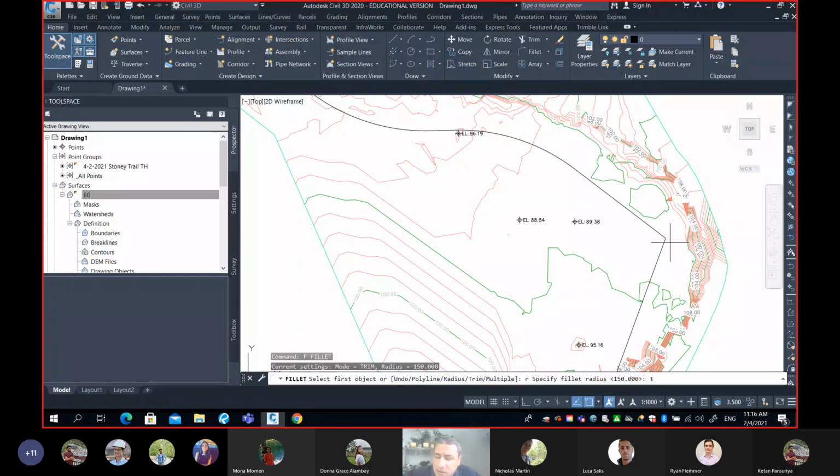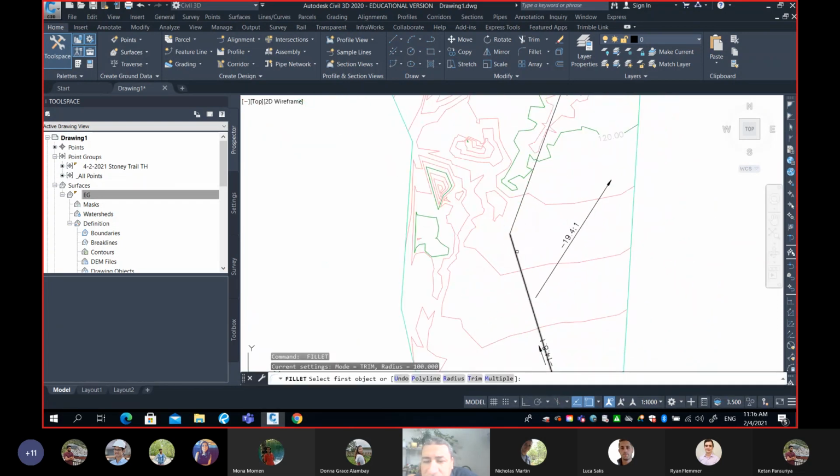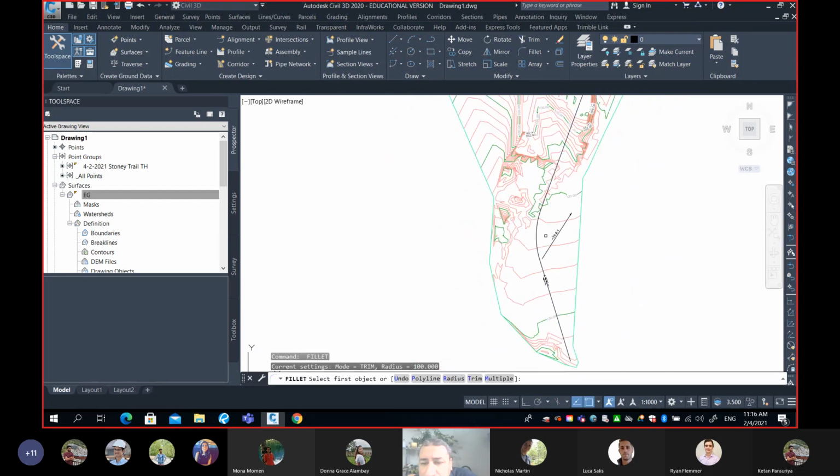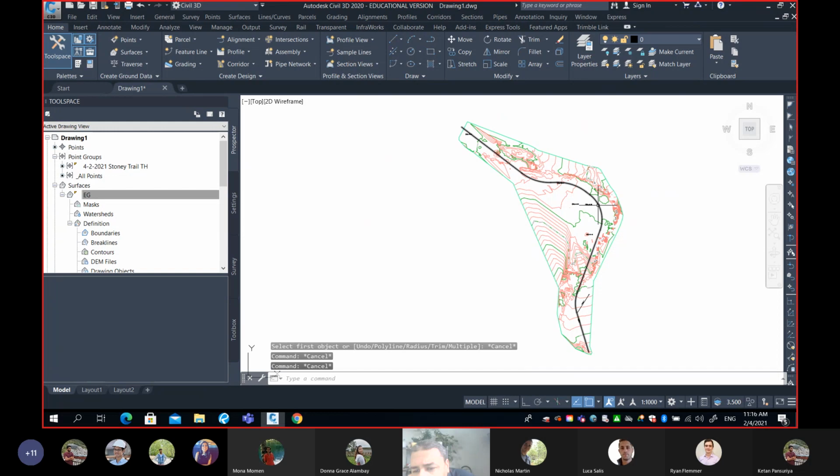So that's very big. So let's say fillet radius 100. Okay. And then finally, we add here another radius. Think about this one as someone who can use this map to come up with the road center line. And again, that's one example.